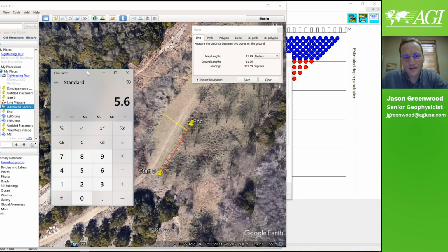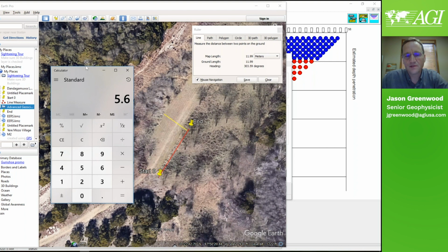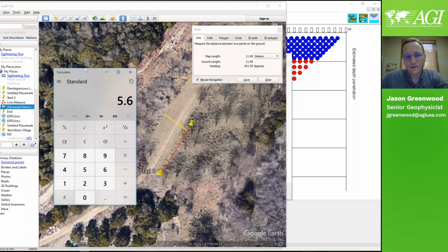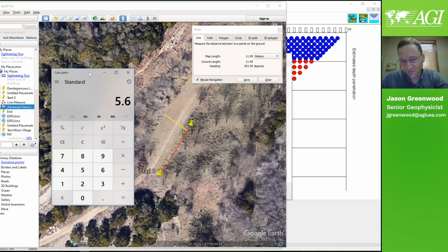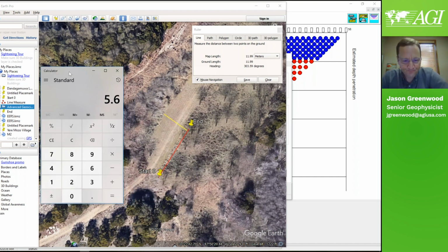And in industry, I can tell you that after a little experience, they much prefer the inline measured 3D, which would be to do it piecemeal. There is a slight loss of resolution, but as long as you get the lines close, not more than, so if this was 1 meter, not more than 2 meters and parallel, measuring across, if you imagine a grid like that, the project is much more efficient.